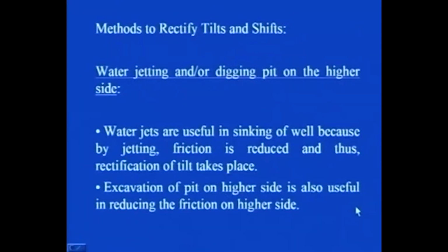Then water jetting and/or digging a pit on the higher side. Water jets are useful in sinking of well because of jetting, friction is reduced and thus rectification of tilt takes place. Excavation of a pit on the higher side is also useful in reducing the friction on the higher side.